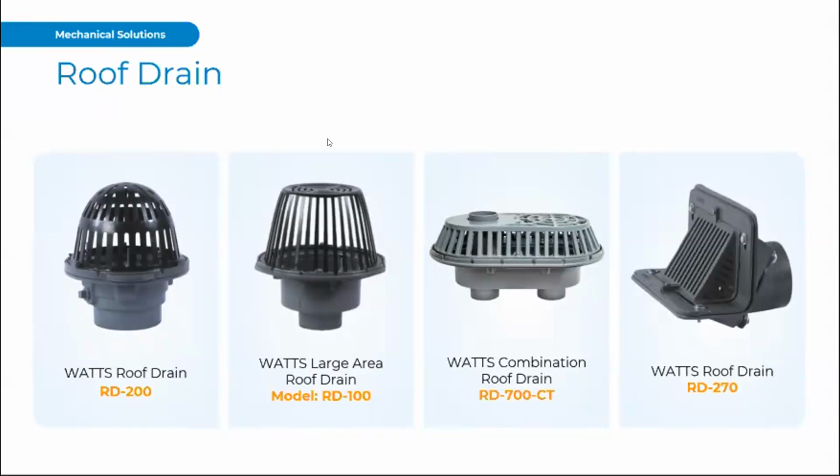Very interchangeable. Again, our masters include a variety of your standard, your conventional roof drain with the flow control, your inverted roof drain, where you may have a lower membrane below the insulation, or your inverted roof drain with flow control. We have our ATS recommendations where we recommend the cast iron dome, but of course a more budget-friendly plastic dome could be available as well. It just would not have the same life expectancy.